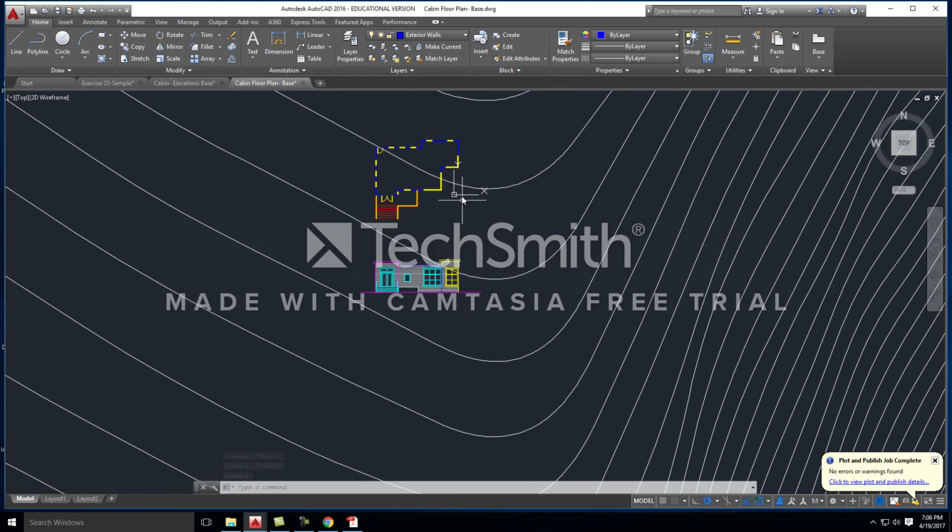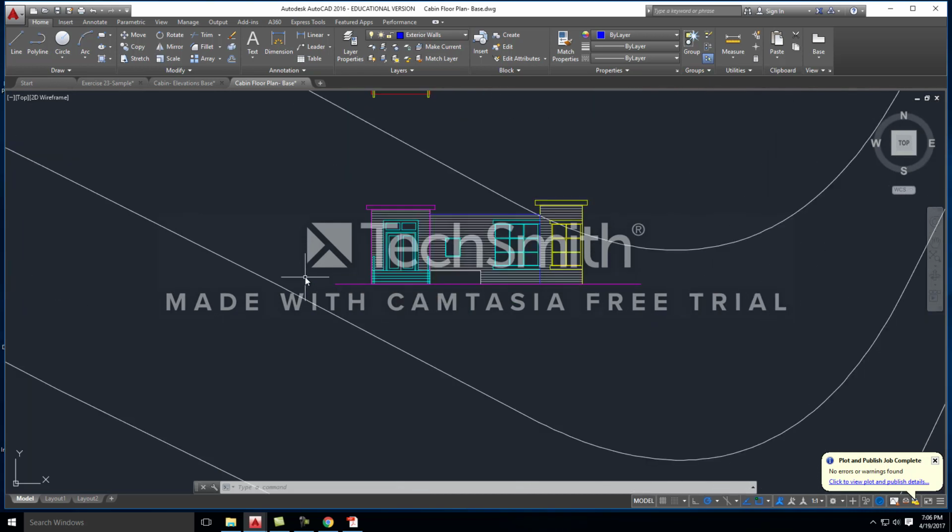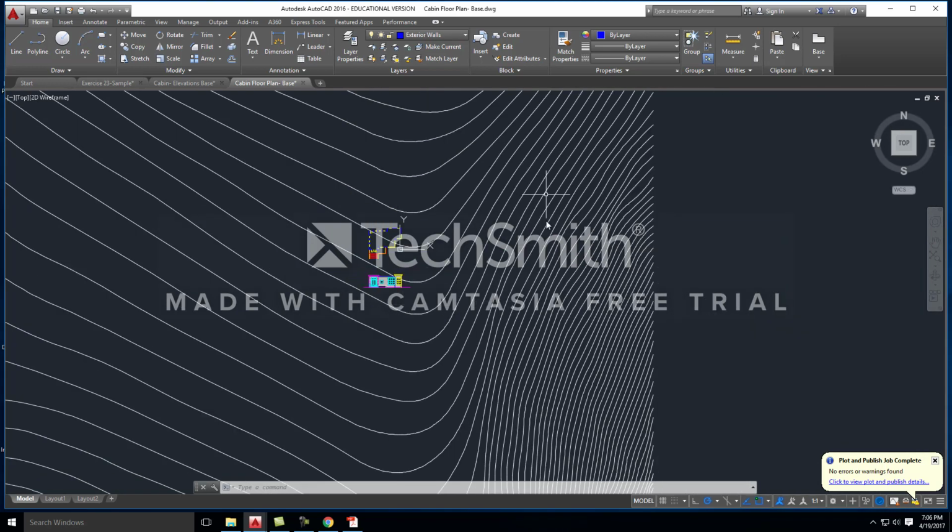For example, right now I have my floor plan right here and I have the corresponding elevation. What I'm going to do to create the actual topography is alter this pink line right here. That represents my ground plane, but knowing the topography that we're working with right now, it's not actually flat. There's actually some slope. So you might ask yourself, how does that affect my elevation? This is going to be the last and final step that you would take to getting a more precise, more dialed in elevation.